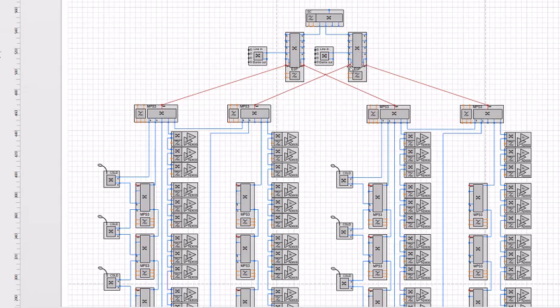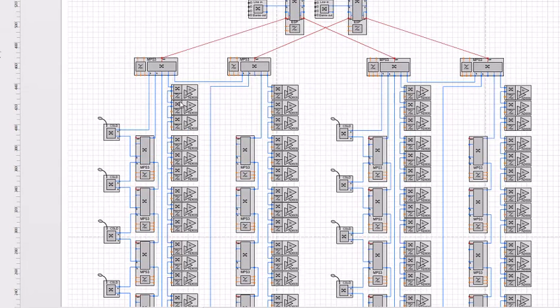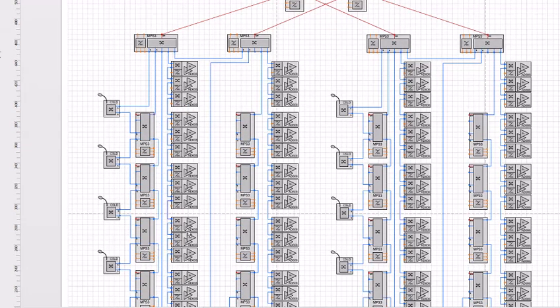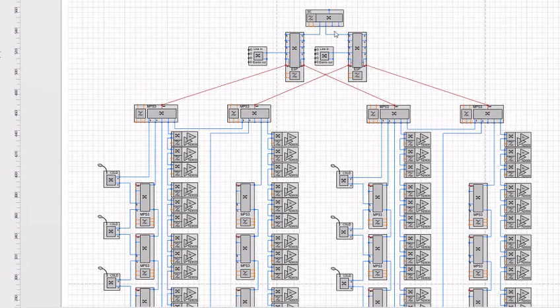Advantech switches have fiber ports. These are two. The system on the left is a remote system. The system on the right is a remote system, and you see that we have glass fibers going to the system on the left and to the system on the right. Yeah? And also here we have redundant loops from the controller via the switch, via glass fiber, via all the devices here, and back to this switch and back to the controller.